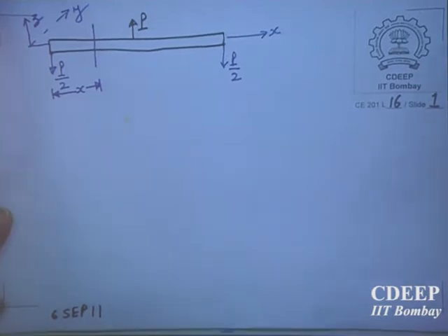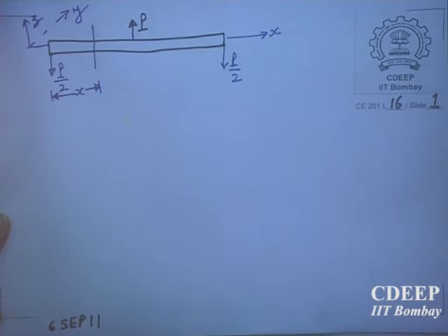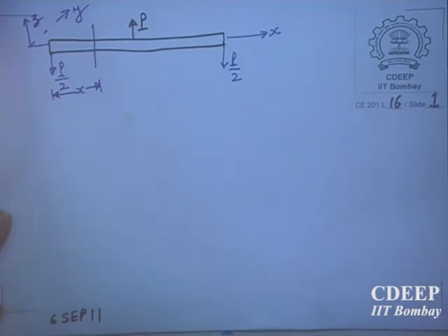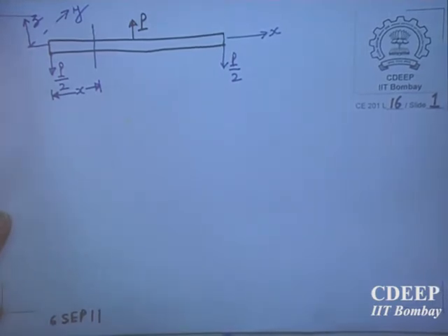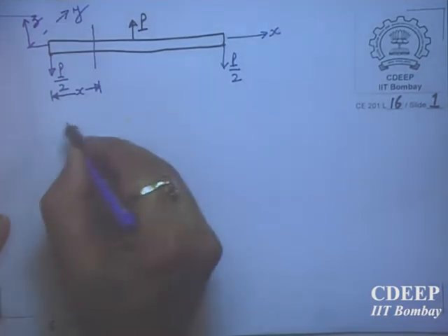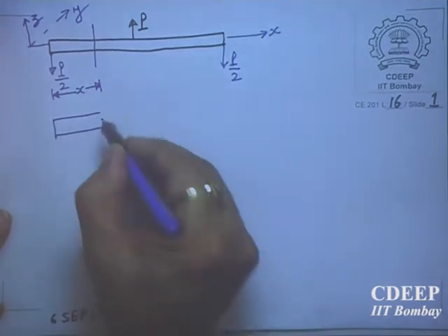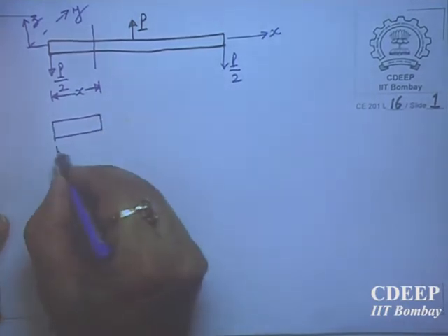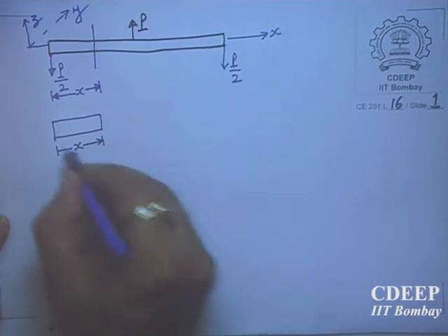Those forces we have taken as normal force and then shear force, and then we said that we define intensity of force as a stress, and so at a point there will be normal stress, shear stress and so on. Now here we are talking about the nature of forces at a distance x from the left end if you cut this body into two halves.